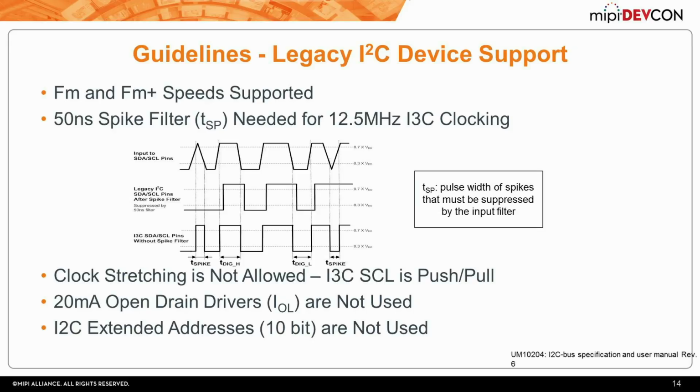Also, clock stretching is not allowed. We found in our surveying of the industry and our own experiences that clock stretching isn't extensively used. Clock stretching was put in place in I2C to allow slave devices to hold the clock low if it needs some more time to execute on something. So if it needs to acknowledge a byte or return a byte on a read, it can extend the clock low.